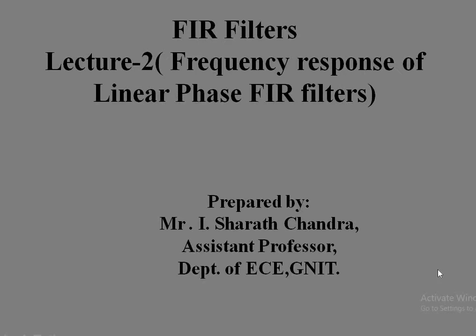We also saw that in practice it is not necessary to insist that the magnitude be constant in the entire pass band, and a small amount of ripple in the pass band is usually tolerable. Similarly, we discussed some key characteristics of FIR filters. We studied FIR filters having linear phase, and we were able to gather 2 points.